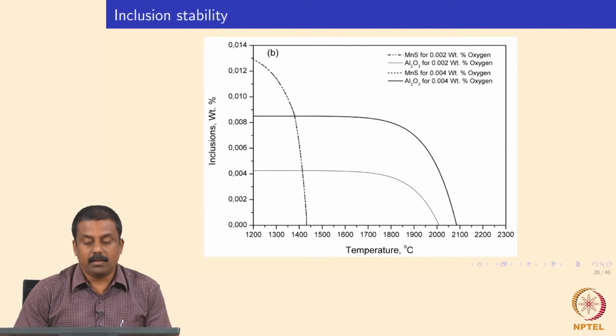And inclusion stability is also affected by the presence of varying amounts of oxygen in the atmosphere. So if you have shielding gas or backing gas in GMAW, or if you cover with backing gas in laser beam welding, the presence of oxygen should be controlled significantly, and if you change the oxygen concentration in the weld regions, the kinetics of inclusion formation can also be changed significantly.